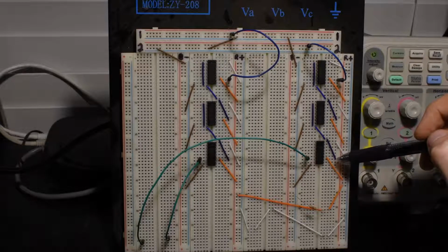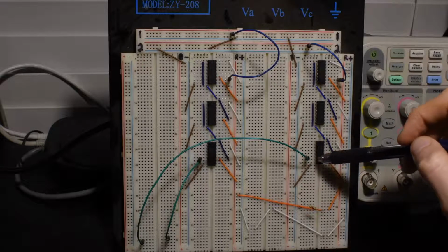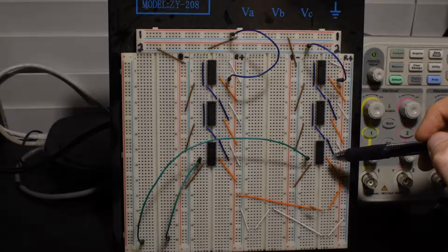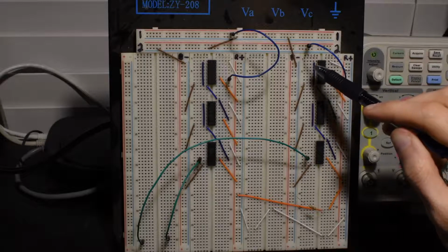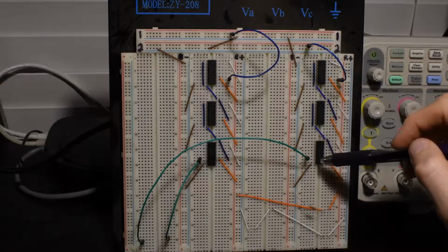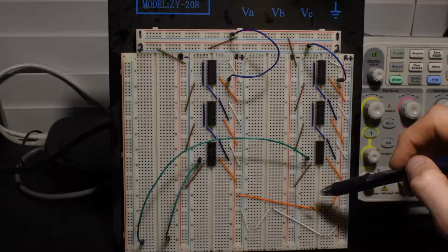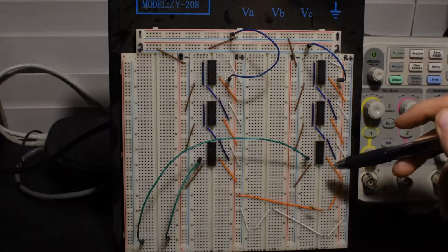And this one connects down here to the clock pin of the next one. And then we're not actually going to use all the pins on this last one. We're going to stop with this one, and by the time we get here, what ends up happening is that we originally have a 10 megahertz clock input here, and then by the time we get here, we get a square wave that goes through a full cycle once every 13.4 seconds.